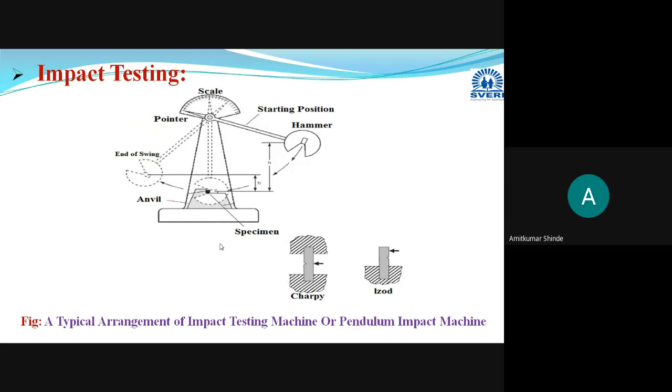Okay, these points you have to write in a simple way. You have to write like this: a ductile material may fail in a brittle manner due to its low capacity, or low absorption of energy, and this low absorption of energy is due to the following three conditions: low working temperature, a high rate of loading, and triaxial state of stress.